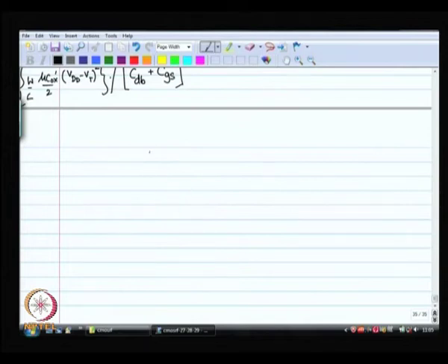Okay, let us draw each stage. It is Gm times Vgs. Here Gm is really the Gm of the NMOS plus the Gm of the PMOS, in shunt with RDS, where RDS is really RDS of the NMOS in shunt with RDS of the PMOS.